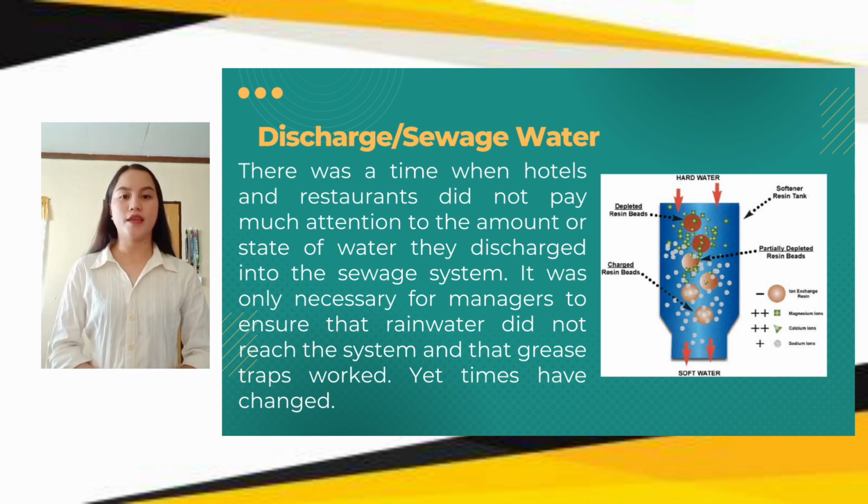They are commonly in particle form, with a diameter of up to 0.5 millimeter. Artificial organic resins are used more frequently in modern applications. These spherical, clear BB-sized resins have the benefit of having a larger number of exchange sites.